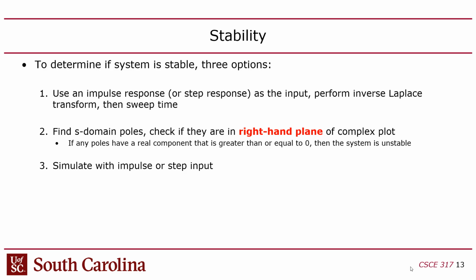And that's what Simulink is doing for you. You can set up these transfer functions, and you just hit simulate, and you can actually plot the signals in the time domain, right? So in this case, this impulse response can be done mathematically, or you have to use a numerical method, like a software package that can do it, right?